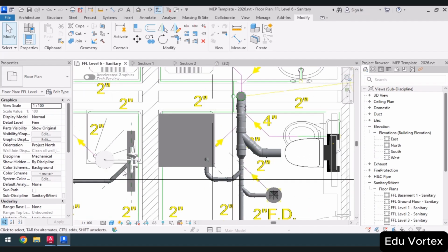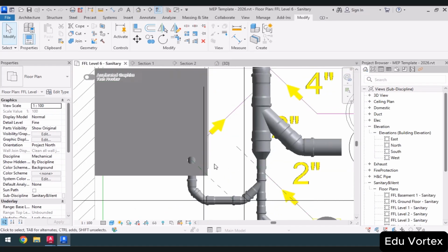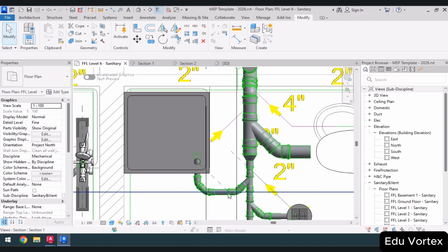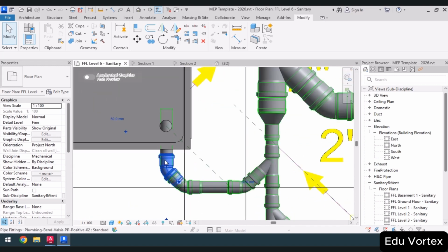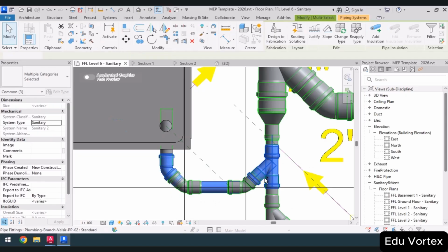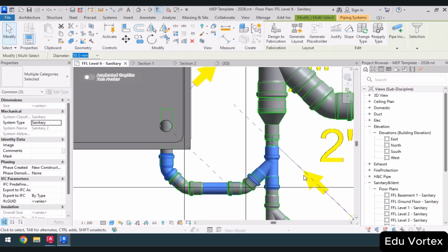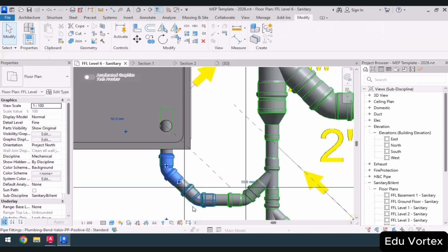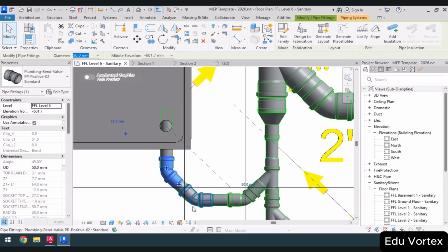Finally, we need to check if we can fit this siphon in this space. If not, we may need to raise everything slightly higher. So I proceed with that adjustment now by selecting these pieces and bringing them forward as much as possible until they reach this limit. So after that, I lower this elbow again slightly.